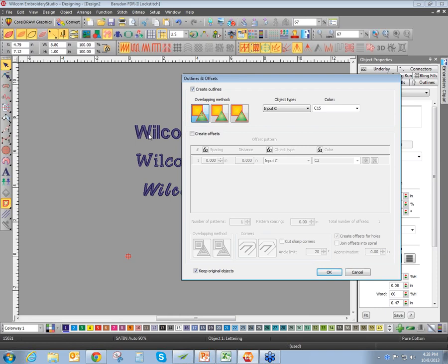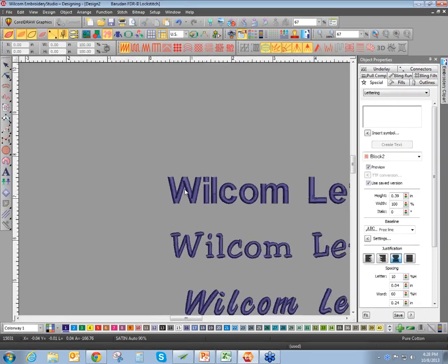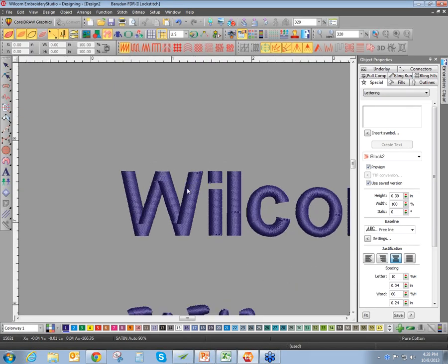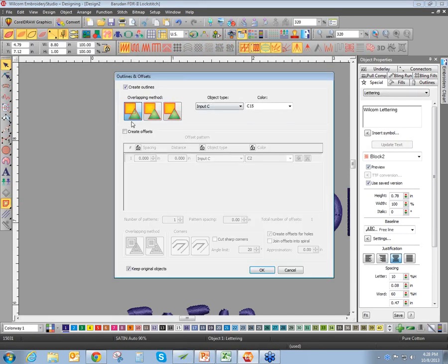Part of the problem we had before, and again with other softwares, if you were to do an automatic bordering or outline, it actually read each letter, or the columns of each letter, as a separate object. So it would have done a 4-part outline, if you will, crossing over each outline, even our object outline here on our W. Whereas now we have welded offsets or welded lines that we can create that intersect. So I can create individual outlines on all outlines created. It would be full outlines.